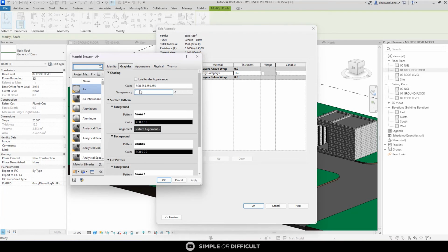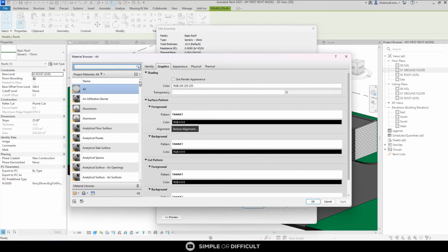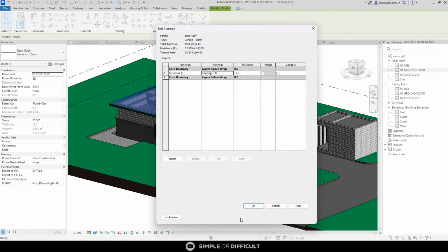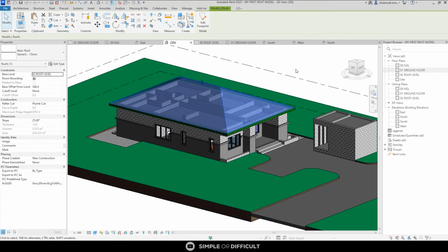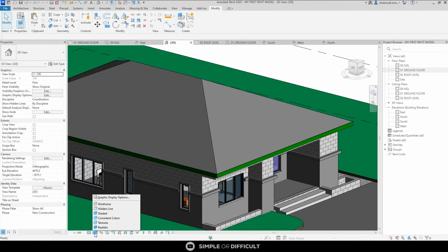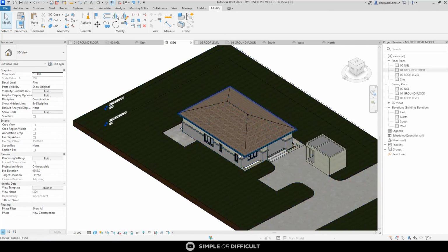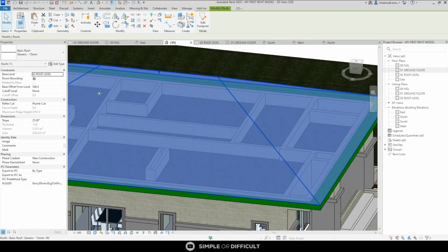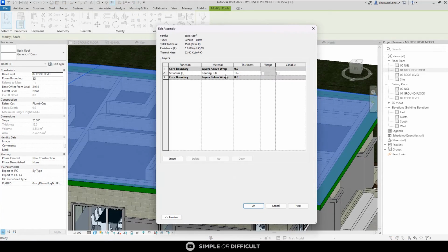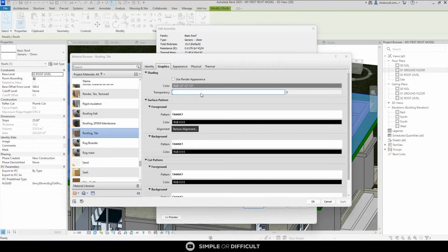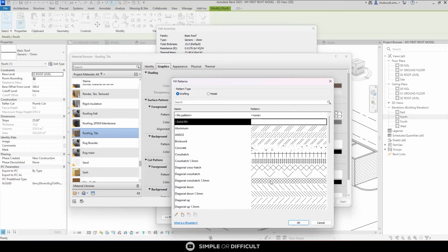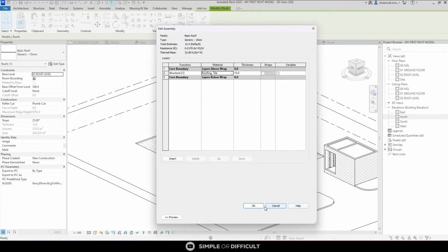When I do that, I can now come over here and select the roof material I want. So I'll just type roof here and see what is available. Okay. Let me select this one, and I'll say okay. When I set it to texture, you're going to see what we are dealing with over here. All right, you see the roof? I want this roof to be displaying even when we are not in the texture mode. I'm going to put solid fill and then use solid fill instead.